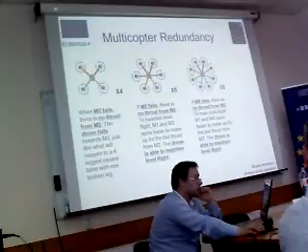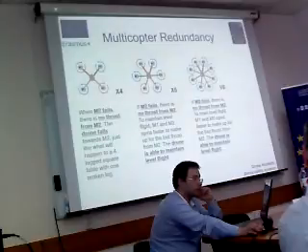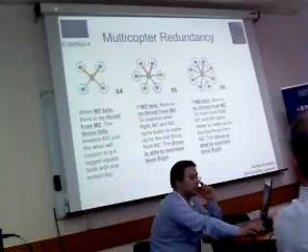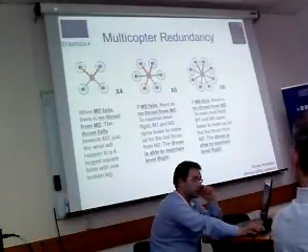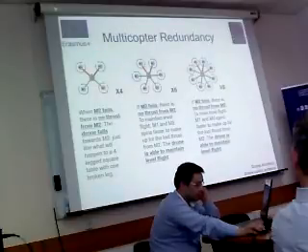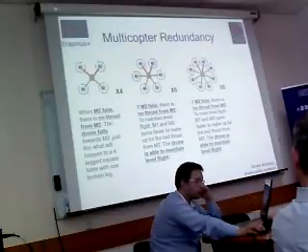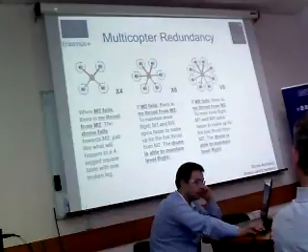And the last solution is the octocopter. This is the most expensive design, but this configuration is less efficient in propulsion. This is because for an equivalent size, a quadrocopter will have more space between motors to spin longer propellers. And of course, in this kind of multicopter, one of the motors may fail.